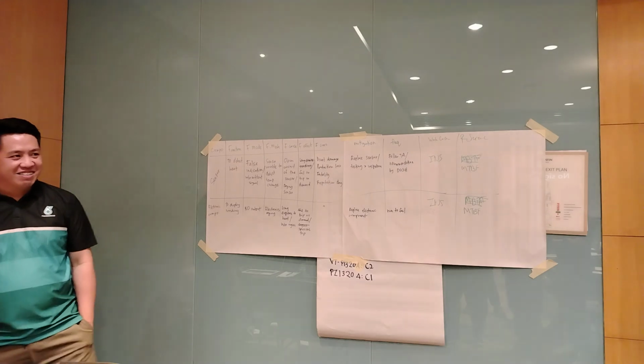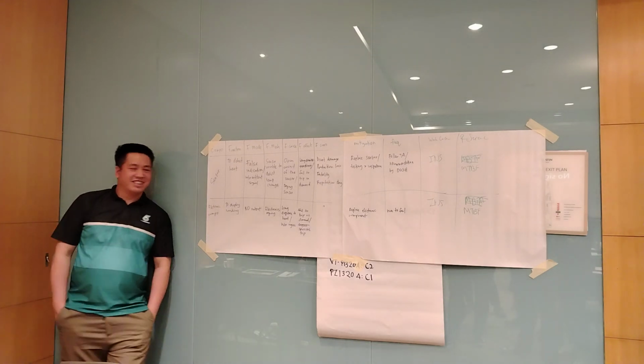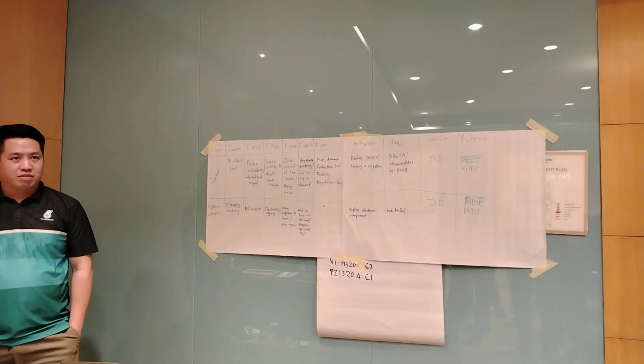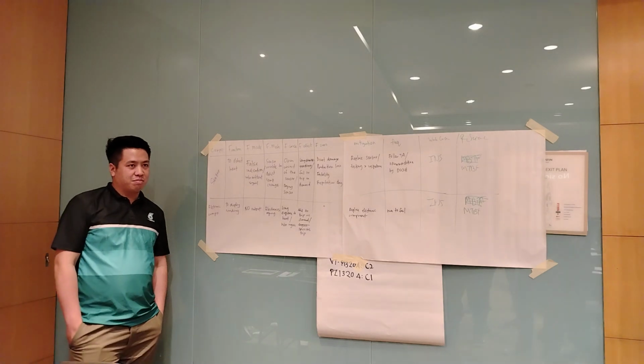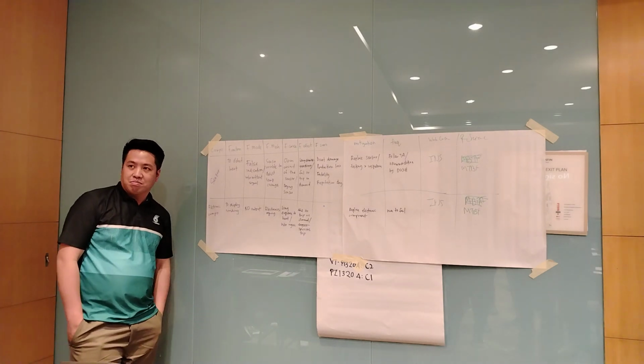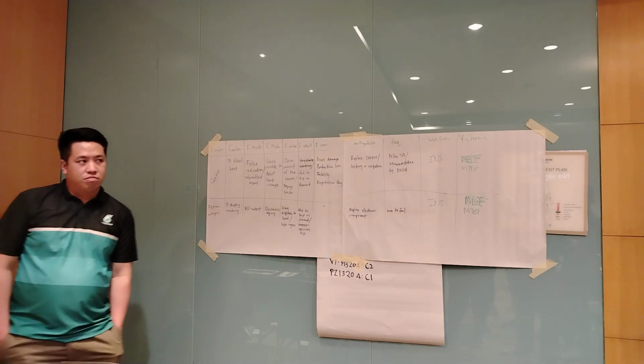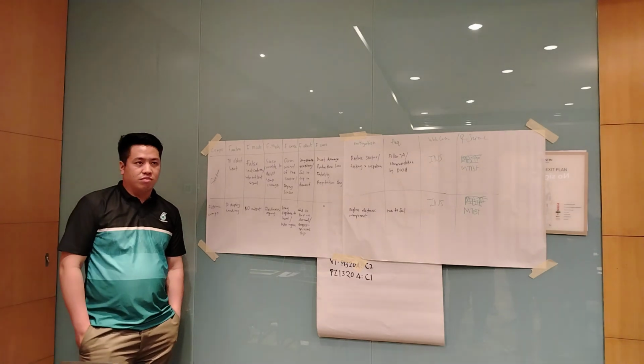How many maintenance strategies do you have? Time based, risk based, or condition based? You only have 3. So they prefer time based because the consequence of any failure to this is huge. Yes.